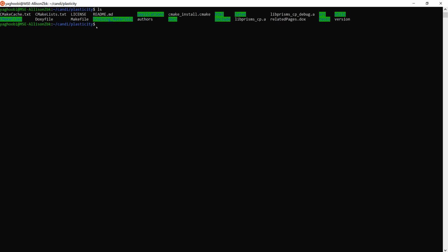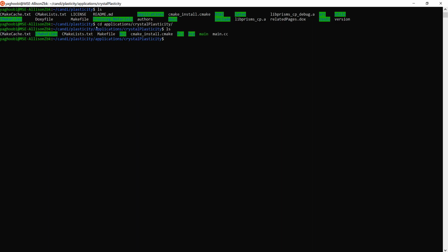I assume you compiled deal.II and PRISMS-Plasticity using the previous video and you git cloned the plasticity folder from the PRISMS-Plasticity GitHub. We are in the plasticity folder right now. This has been compiled before, so we want to go to the applications folder, crystal plasticity. These are the applications we have in this folder for different crystal structures. Let's start with the simplest one, FCC compression.